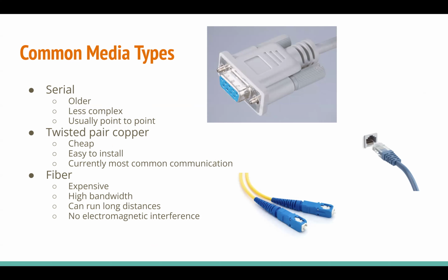We have reasons why we would want to choose any of these. I'm not going to go way too in depth with this. As people who've taken my class understand, we can talk about this stuff for a very long time. I'm just going to give you the high level points. So serial is old, and that's one of the reasons it's still out there. In the utility world, we have a lot of old stuff kicking around. They didn't have cheap twisted pair terminations at that time, so they put serial on the equipment back then. We still have relays from the late 70s and the 80s in plenty of substations. So that's one of the reasons you'll see a lot of serial.